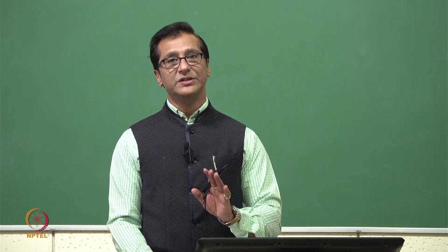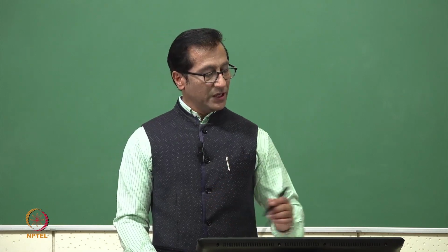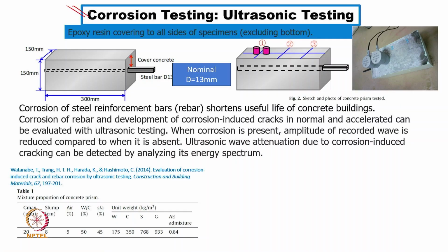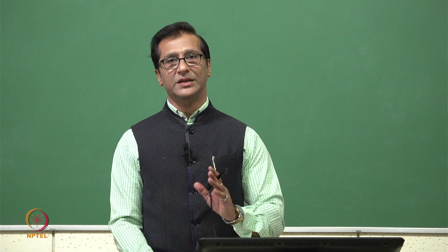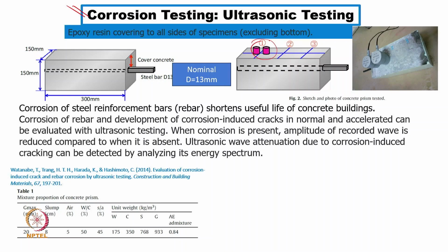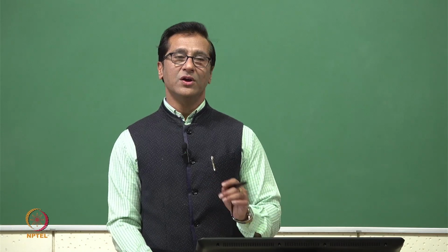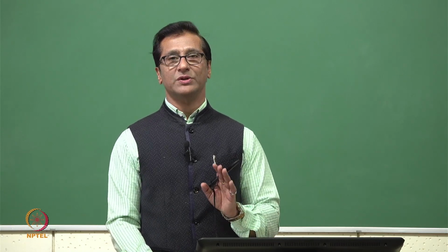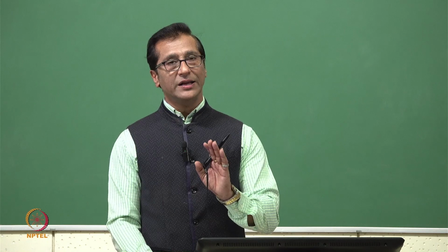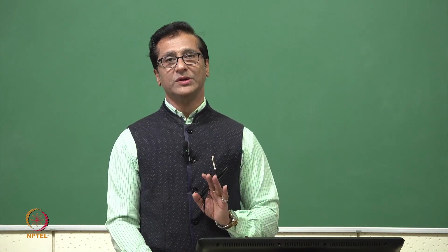So testing is very essential for this. One is radiography testing that people do. I'm just going to describe in one or two slides particularly UT, that's ultrasonic testing. We use two sensors. One sensor sends a signal, the other sensor captures the signal. Now in the ideal, perfect case, we know what will be the microsecond, how fast we should get the response and what kind of response we should get, and we compare with the actual case.